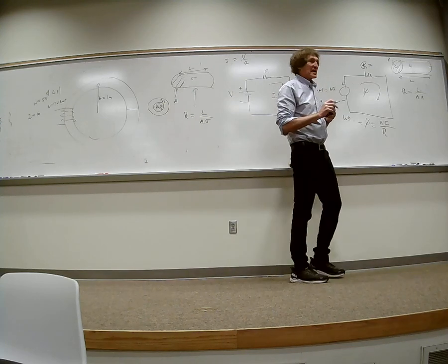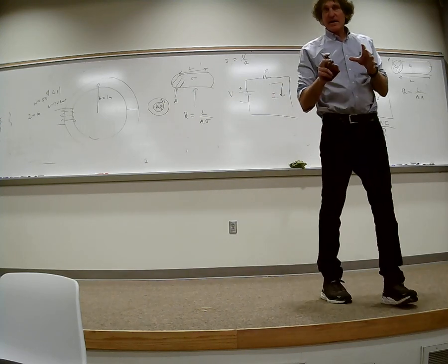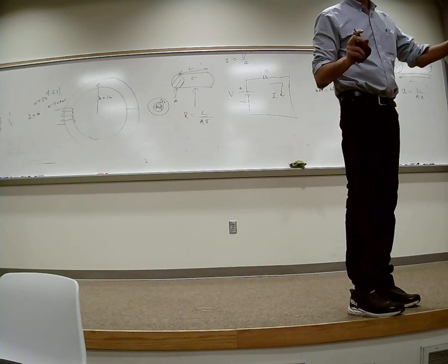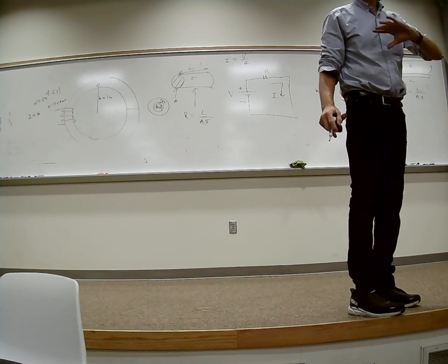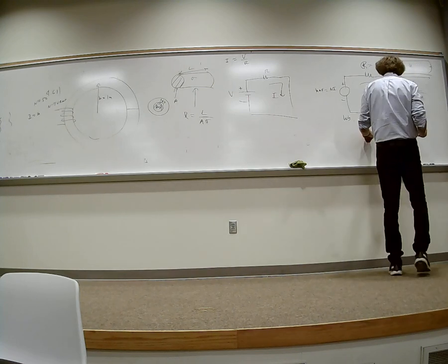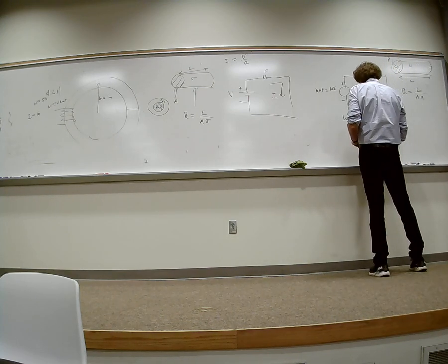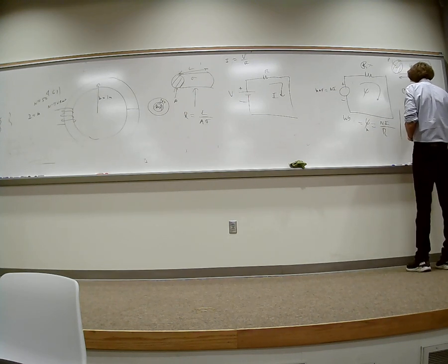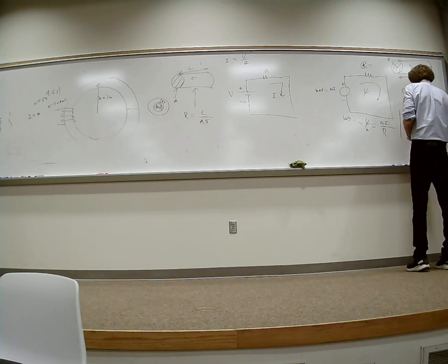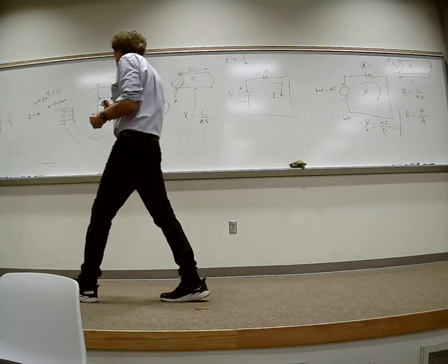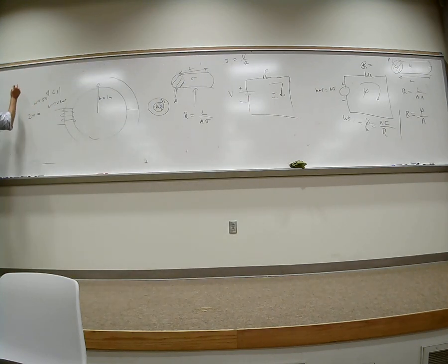Now, if that's the magnetic flux, please just listen. I've got the magnetic flux, right? How did we get the magnetic flux before? We integrated B dot ds. Do you all remember that? So if you wanted the B field, once you had this, you can find the B field to be equal to the magnetic flux divided by the cross-sectional area of the material. Now, in truth, magnetic circuits really look like something like that, but I'm going to make it simple. Normally, they'll do it this way.